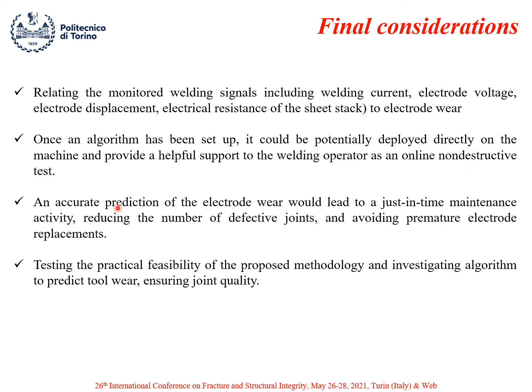This is good because it allows to have an accurate prediction of the electrode wear that would lead to a just-in-time maintenance activity, and also the possibility to check each spot weld. Because when you realize the joining process and you are analyzing the weld spots, you can immediately have the welding signals, and these welding signals can be elaborated by an algorithm, and this algorithm can say you if the electrode is too worn or not, and if the joint obtained is sound or not.